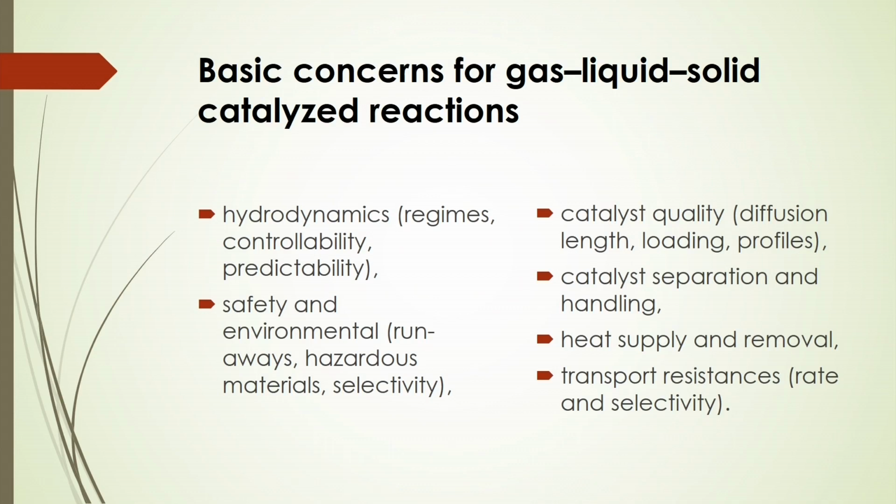Now, you have to remember some basic things for these gas-liquid-solid catalytic reactions. What should the hydrodynamics be, like regimes; if it is gas-liquid reactions, then what will be the size of the gas slug, what will be the size of the liquid slug. So, you have to control those things to get an intensified process output.